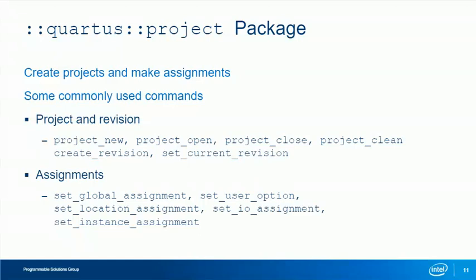You can use the assignment commands listed here to make both general assignments that apply to the entire project, or design-specific assignments that apply to specific design nodes or entities. As an example, the set_location_assignment command can be used to make pin assignments.